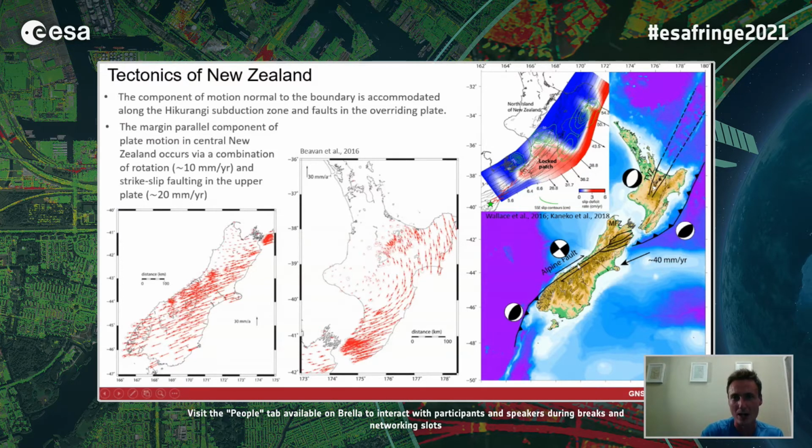As well as the subduction, where New Zealand's quite well known, we have a lot of slow slip events. In this figure, these are shown in these green contour lines, and these tend to hug the lower limits of the inferred lock zone that's been derived from 20 or 30 years' worth of GPS measurements. If you look at the GPS velocity field shown on the left for the North Island, you can see this nice clockwise rotation of the forearc. As you transition into the South Island, we then get this very nice strike slip motion across the Alpine Fault.